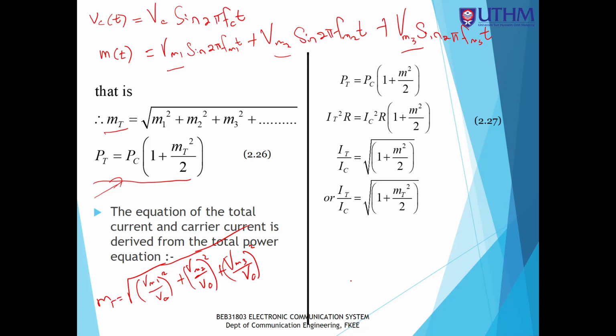Okay, we're gonna have 3 pairs of sideband, which is 6 sideband, 3 upper and 3 lower. If you want to draw this kind of question, it looks like this. For example, this is V versus F, and the carrier is here, carrier as usual, Vc. And then we have the first input message.